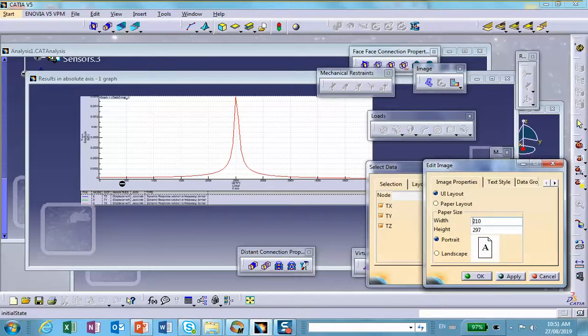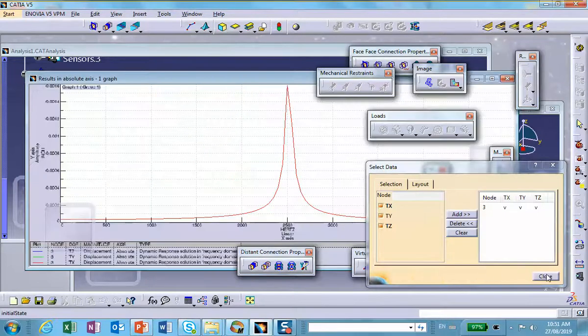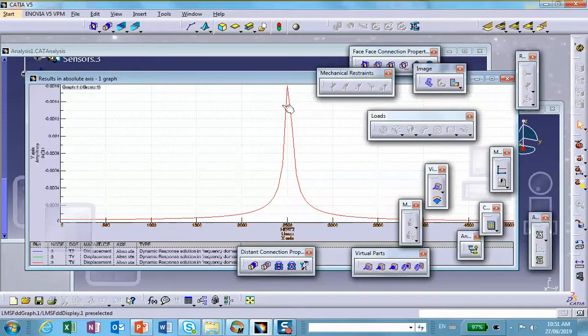It looked like the amplitude was constant, but here's the situation. I told you I'm going to come back to that peak and discuss it, and this is the time to do it. Now, what you have here is the resonant frequency. In other words, if the frequency of the applied load, that big omega, happens to match this frequency, and I bet this is the first frequency in hertz that you calculated for axial deformation, then you're going to get resonance.